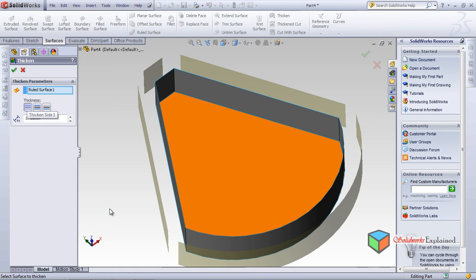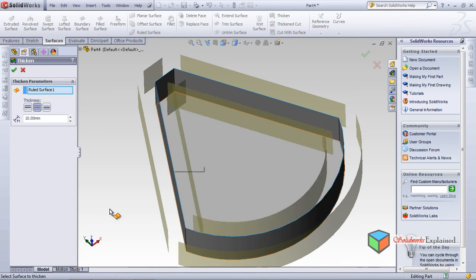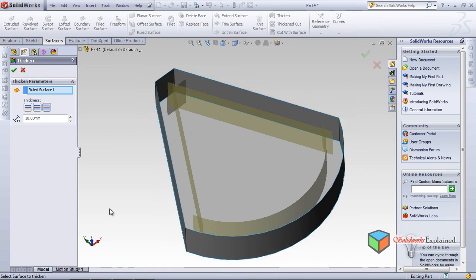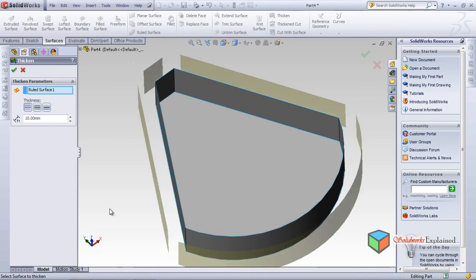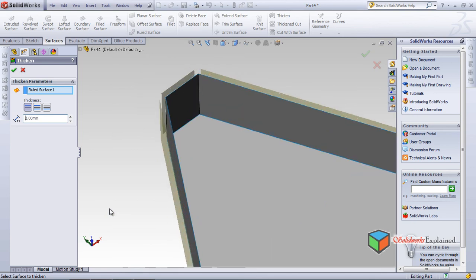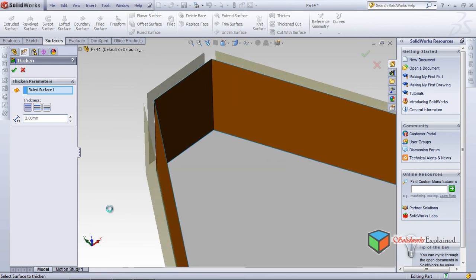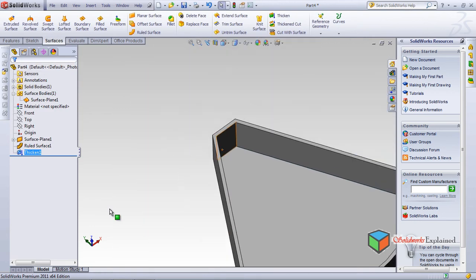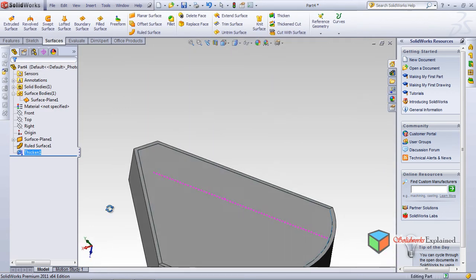here it shows when you zoom in, blue line, black line, yellow line. Now when you click on the center, thickness goes to both sides. You can add thickness and then make the surface solid. So this is the option to make surfaces solids, and only from the inside. So where you want to increase it? I want to make it only from the outside. I don't want 10 millimeters, I just want 2 millimeters. When you zoom closely and make it okay, you're adding thickness, and yes, your thickness is done.